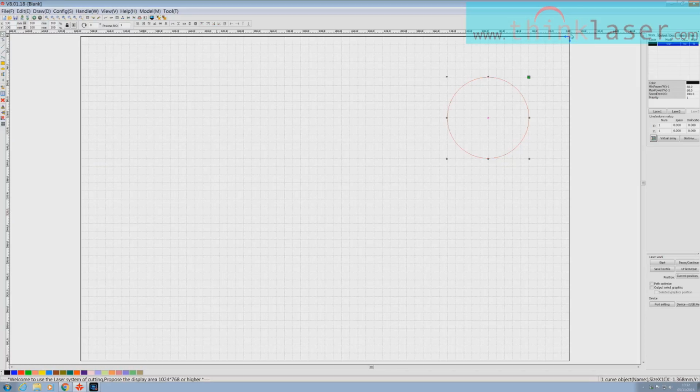So this is truly machine 0, 0, and this is a coordinate. Although we've defined it as 50, 50, in real terms it's minus 50, minus 50, but that's only for programming purposes. But hang on, we didn't set that corner at 50, 50. We told that corner to go to 100, 100. Didn't we?